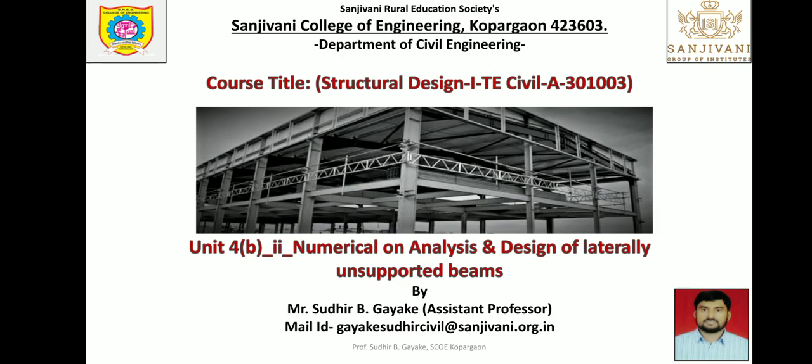So in the present video, we are going to see a numerical on analysis and design of laterally unsupported type of beams. The numerical statement for the given laterally unsupported beam is: design a laterally unsupported I section beam with simply supported ends of an effective span of 6 meters and subjected to working imposed load of 35 kN per meter. Assume that full torsional and warping restraints are provided at support.